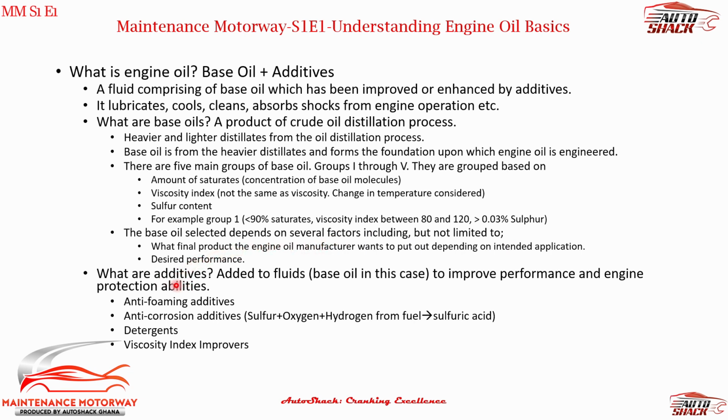Speaking of additives, they are added to fluids to improve performance. In this case, we are talking about base oil additives or oil additives. There are also additives added to fuel, but we're just talking about oil additives for now. If you look at this, we have anti-foaming additives. When oil is allowed to foam, you get air bubbles in it, and that reduces oil pressure. Reduced oil pressure leads to accelerated engine wear, so you don't want that.